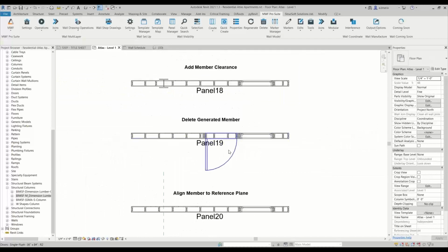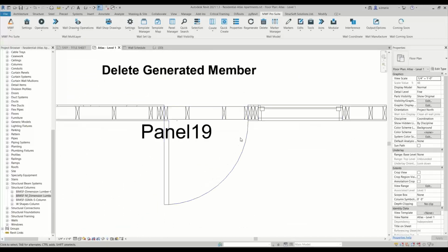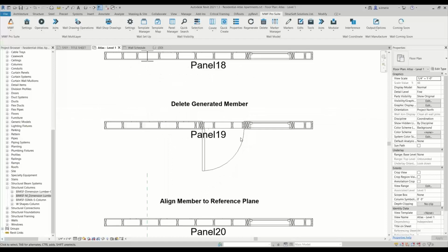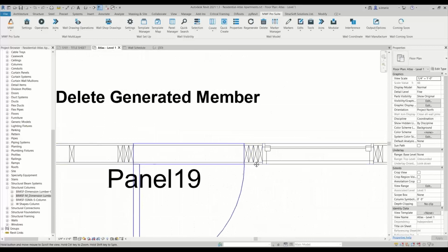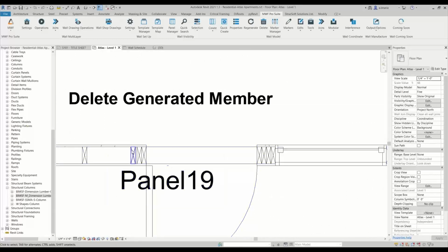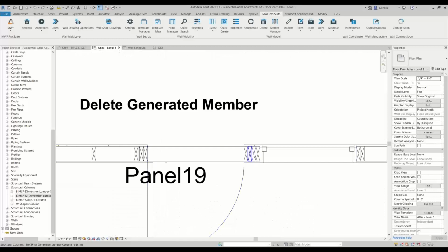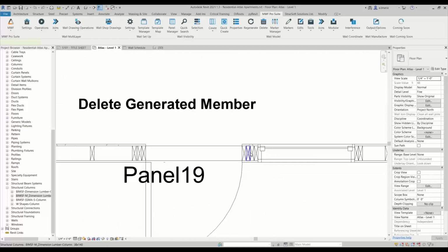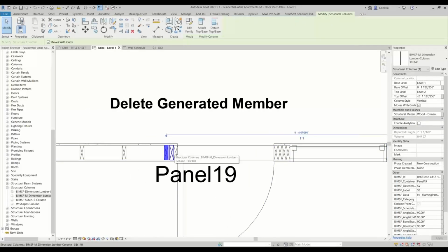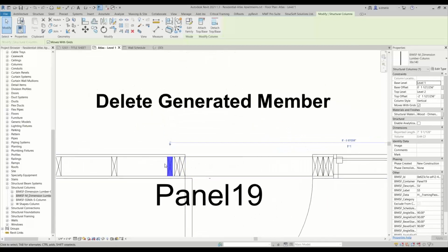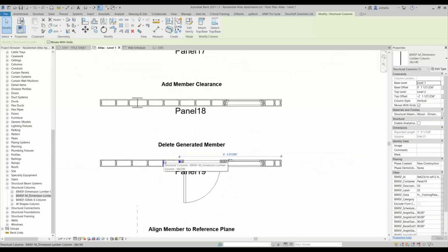But something happened here and that did not work out very well. So we might have to redo that. So let's undo and see how we can fix this issue, right? Over here, we have like triple studs. We have too many studs here. So maybe we want to get rid of only one stud in this location, or we probably want to just get rid of this guy here because this looks too congested, I would say. So let's get rid of this wonderful stud here. It did nothing, but we just don't want it in that location.